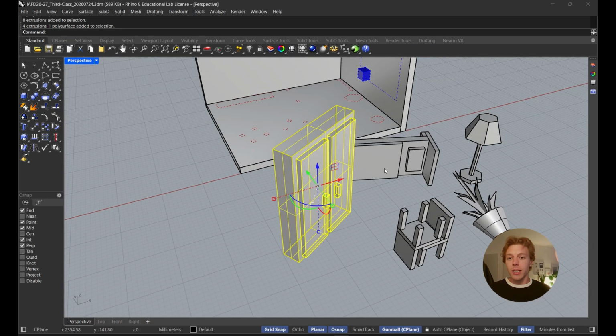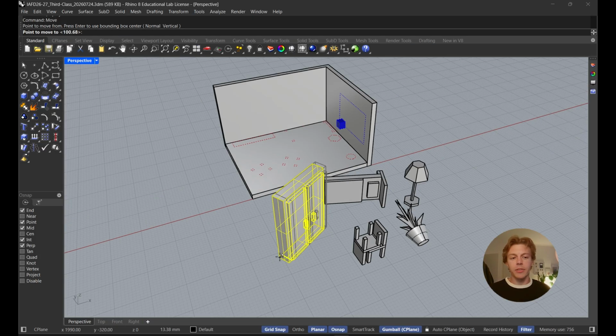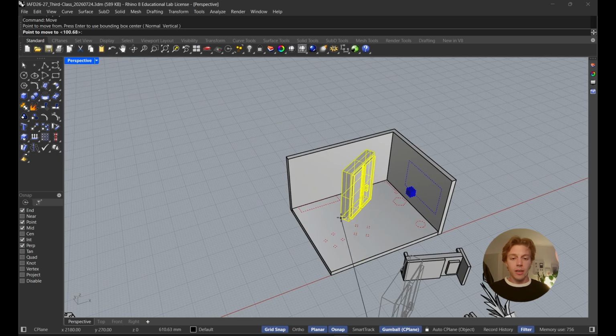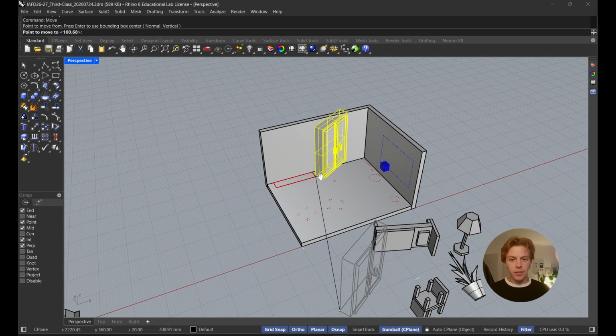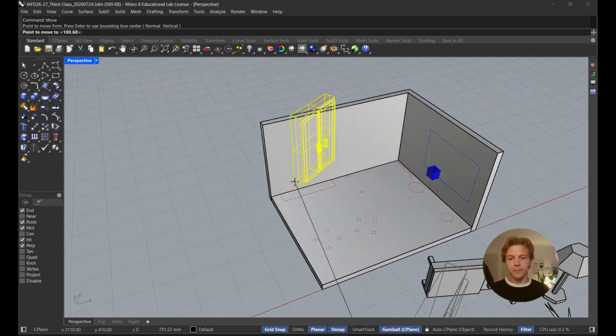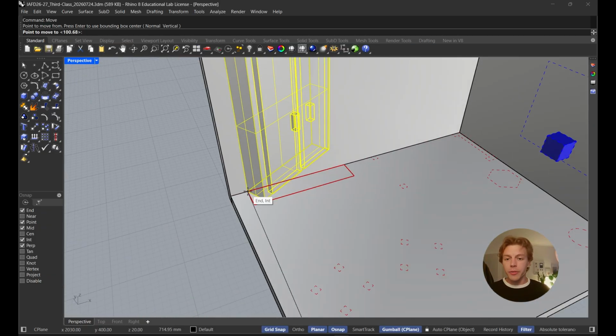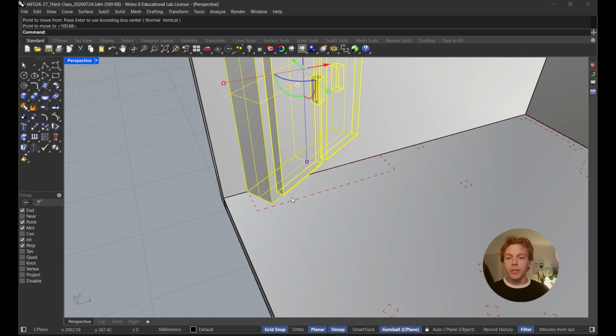Well, again, this is just an exercise of rotate and move. You don't need to use scale because the furniture doesn't have to change size. So let's just begin. Let's pick the wardrobe as the first object. Let's type in move, pick one point that we want to use as our reference. Again, if you want to move your camera in the perspective view, you do so by holding Shift and right click in the mouse. Let's zoom in until we find here the correct spot.